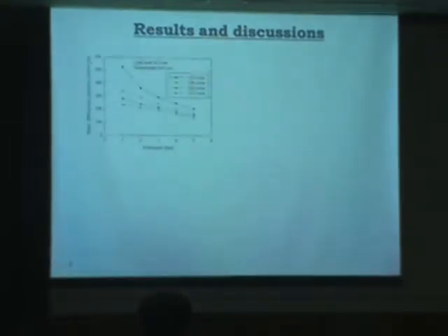Results and discussion. As pressure was the prime parameter in this study, the riser differential pressure decreases with the increase of the system pressure from 1 to 5 bar absolute. This is because of the contribution of the high density of the gas at high pressure. When we increase the pressure, due to the change of gas density, the riser differential pressure was supposed to decrease, and the effect was more pronounced at high velocity.